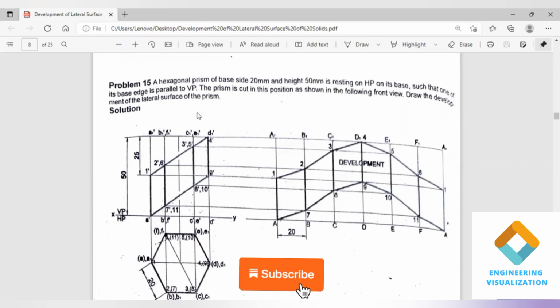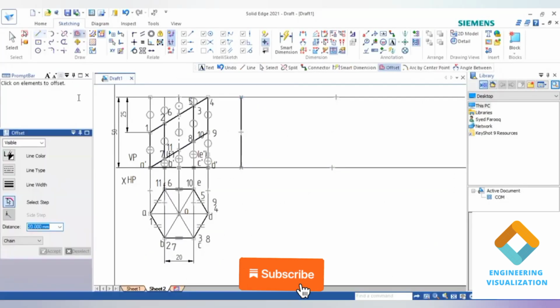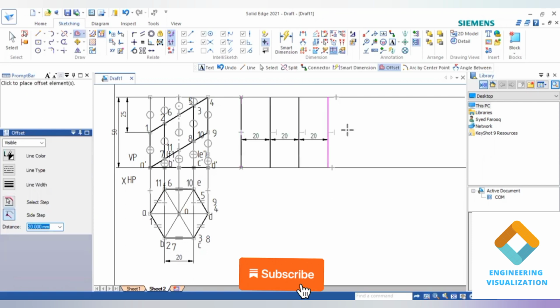You can see this is cut, so that means the front and top view will be given in the question. So we need to draw only the development for this. So the vertical line is drawn. Now using the offset command, I'll be offsetting this vertical line for a distance of 20 mm. There are a total of 6 faces I'll consider here. 6 faces we are considering.